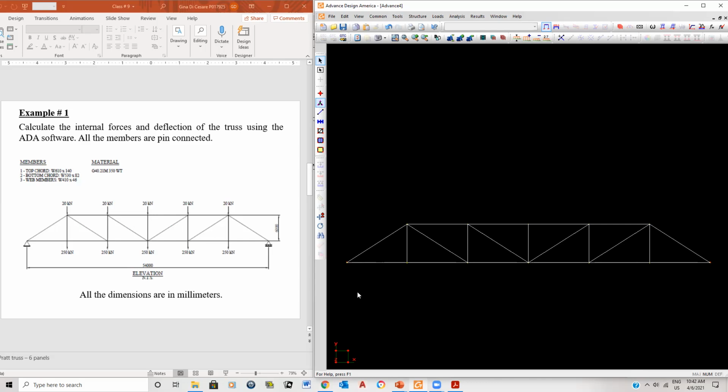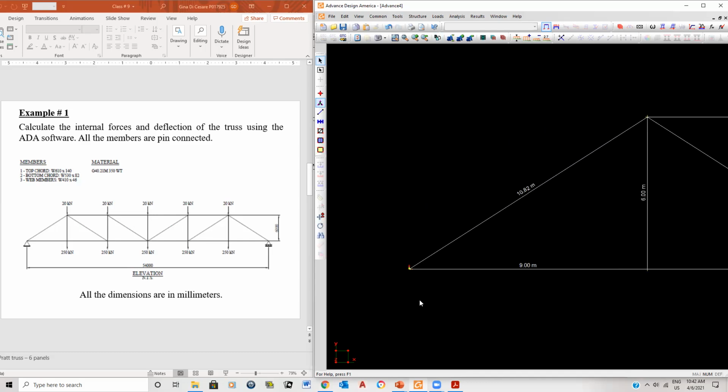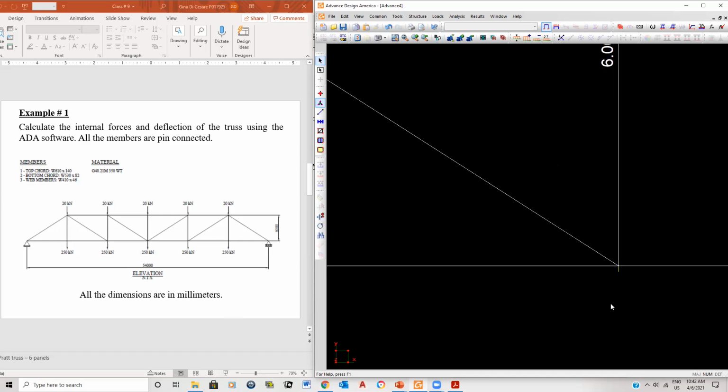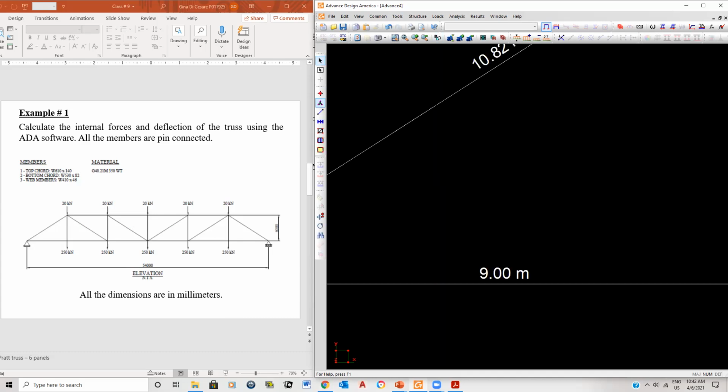The way you could have seen it on the screen is that supports have red, red, red. If you didn't see that on the screen, that means you hadn't changed this into a support node. That's how you can graphically see if you did it properly. Here, for example, it's yellow, no longer red, and these two used to be red, now they're yellow, so that's a pin. If I go to the other end, I'm going to have only one yellow line and a red dot, and that's what I should have at this end.